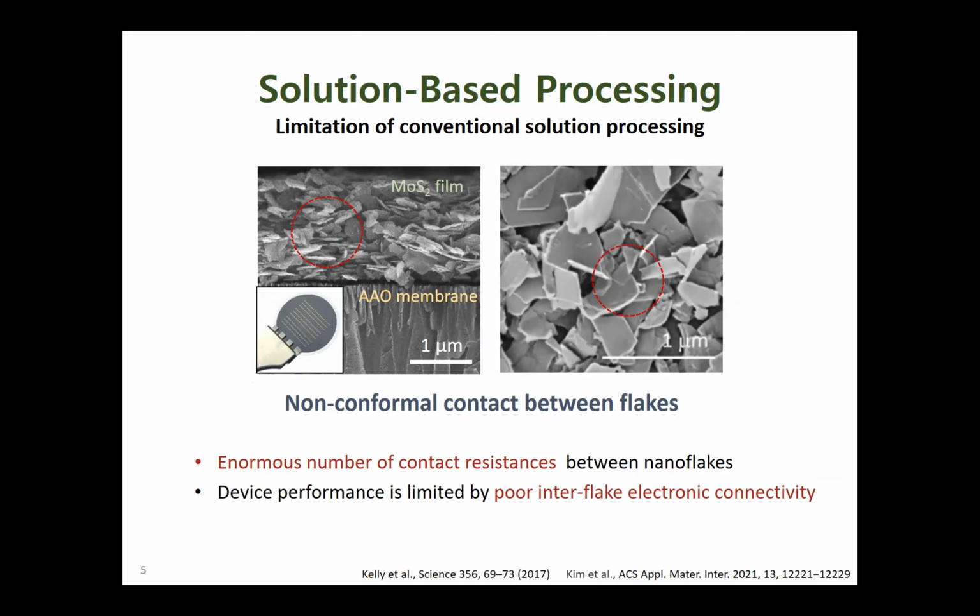As a result, solution-processed MoS2 thin film devices cannot fully duplicate the intrinsic properties of MoS2 discovered from mechanically exfoliated high-quality samples. It is a major bottleneck in the development of solution-processed thin film optoelectronics. So, interface issues must be improved.